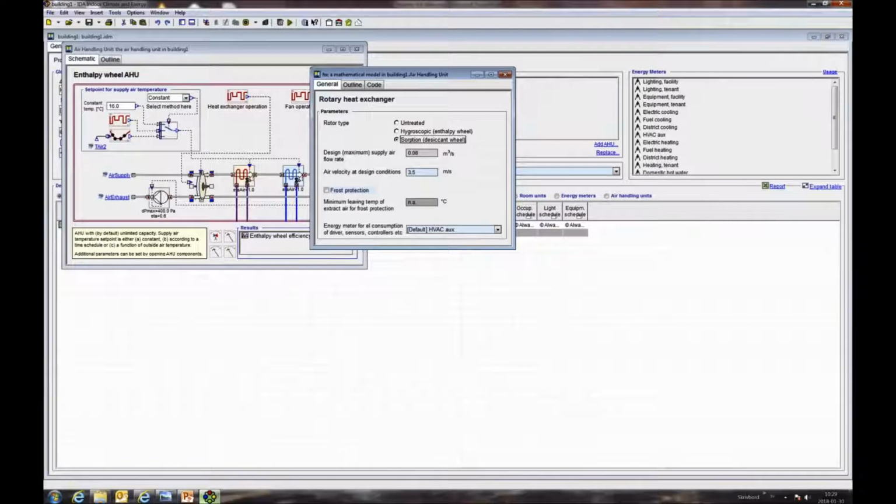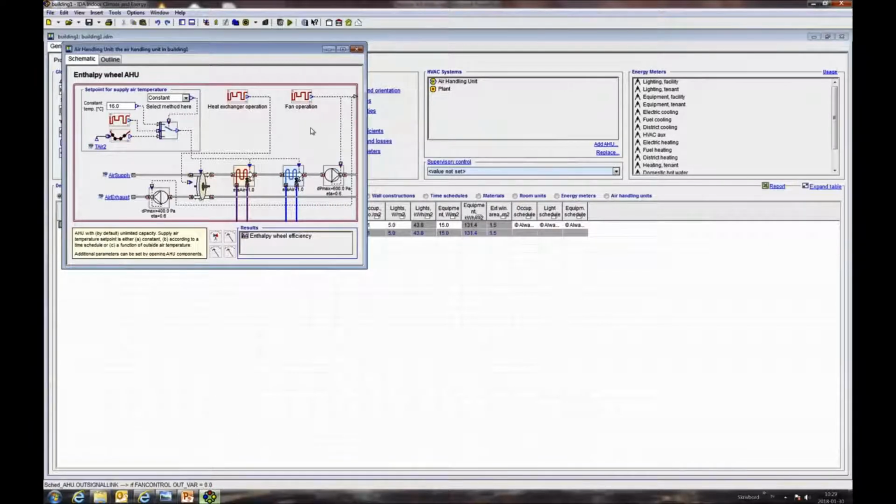So what happens in a model? During wintertime, when spaces are in heating mode, and the outside air is cold and dry, the moisture recovery will help to increase the relative humidity in the zones, thus improving comfort for occupants. During summertime, it's the other way around, so the outside air is warm and humid.